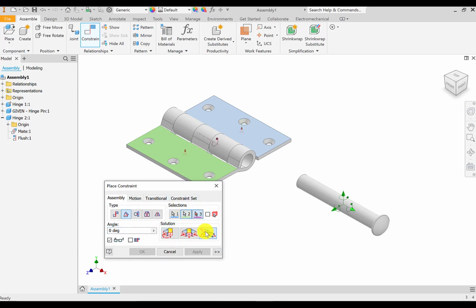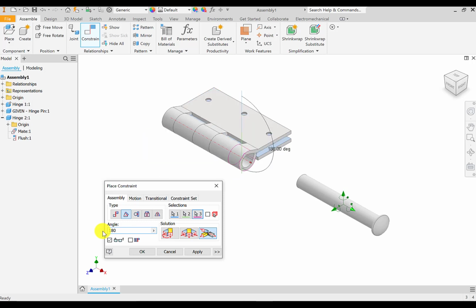Another option is to use the explicit reference vector, where we have to make a third selection that will represent the z-axis or cross product of our first two selections. In the directed angle constraint, this z-axis vector is inferred, which means that the direction of our angle might have to be flipped, like negative 180 degrees instead of 180 degrees, whereas with the explicit reference vector, it is explicitly selected, as the name indicates. In most cases, the best choice of this third z-axis vector product selection is the axis about which our first two selections are allowed to rotate.